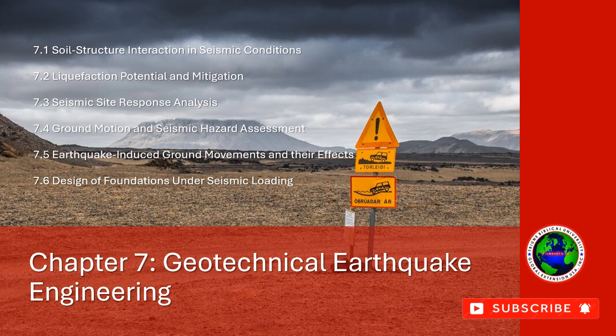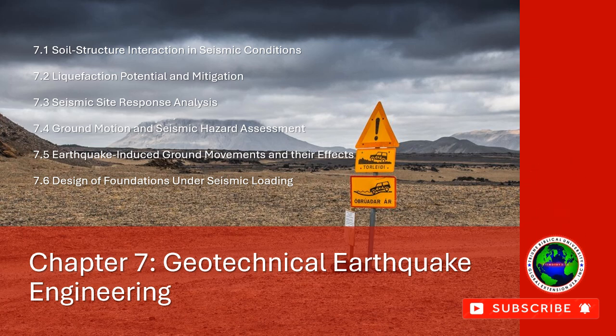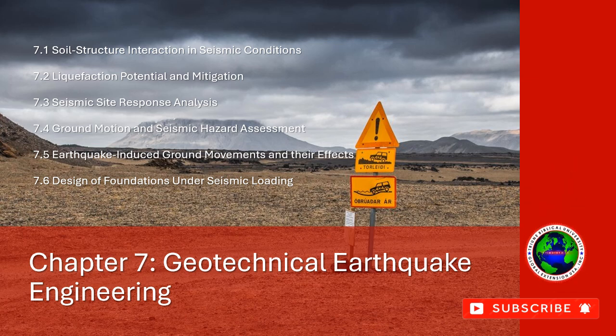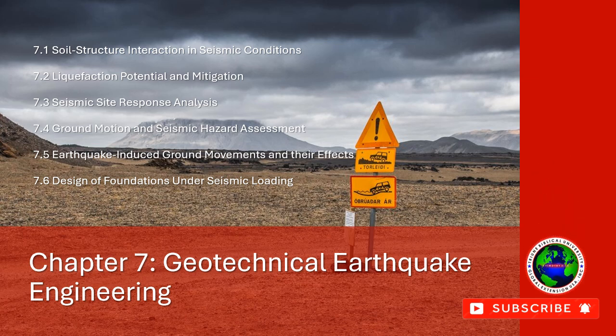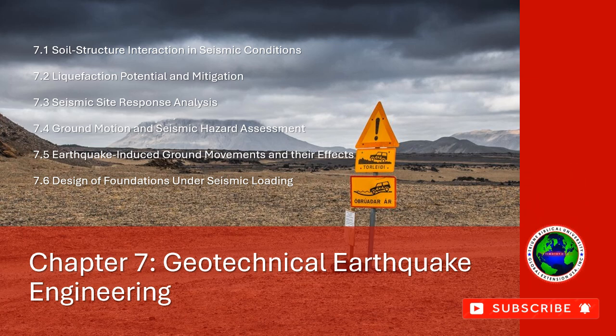2. Foundation flexibility and damping. Foundations must be designed to have a level of flexibility that allows them to absorb and dissipate seismic energy. This can be achieved by including materials or design elements that introduce damping, such as base isolators or flexible joints. The goal is to prevent excessive vibrations and avoid resonant frequencies that could amplify seismic forces.